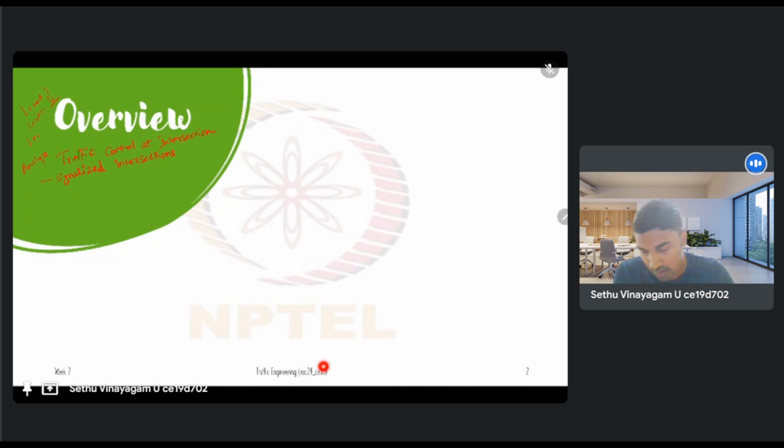And then level 3, which is the signalized intersection, used when you have a high amount of traffic flow that you want to control and a lot of conflicts present in the intersection. So we go for a higher level of control, and therefore it is also the more complex type of control to analyze with respect to the other controls that we have.